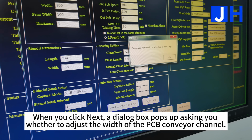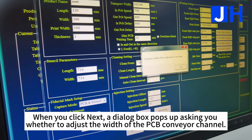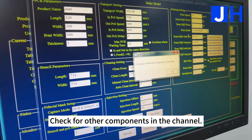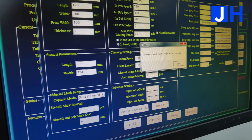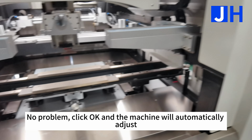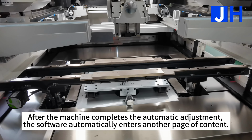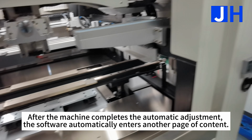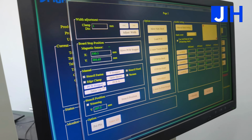When you click Next, a dialog box pops up asking you whether to adjust the width of the PCB conveyor channel. Check for other components in the channel. No problem, click OK and the machine will automatically adjust. After the machine completes the automatic adjustment, the software automatically enters another page of content.